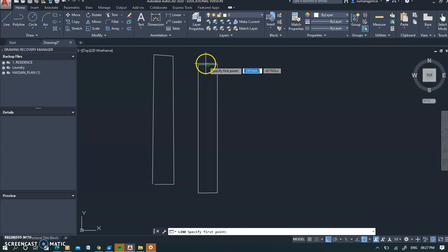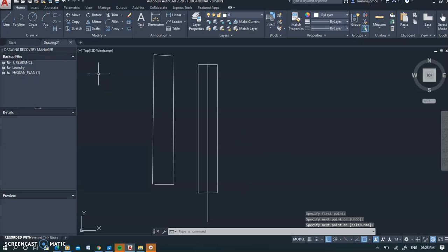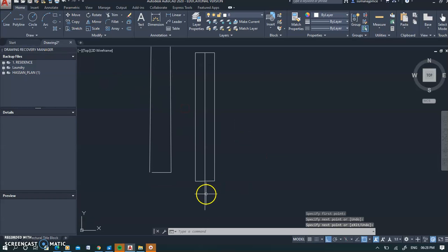So right now I will draw a line just for reference. Now I should not have drawn it so long. Wait, I'll click on it. Okay, I'll activate this. This is a stretch command, and I'll bring it here. So that's done. Now I will offset this by 0.1.